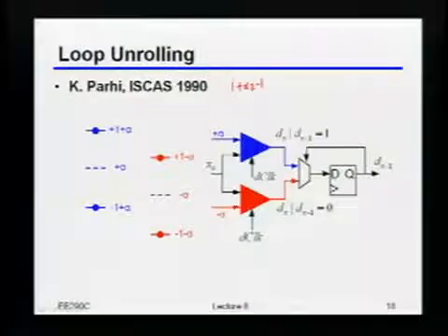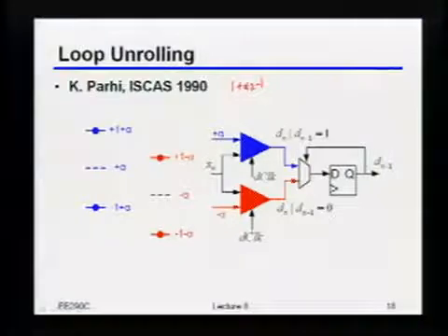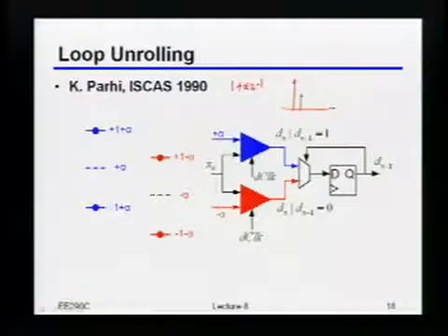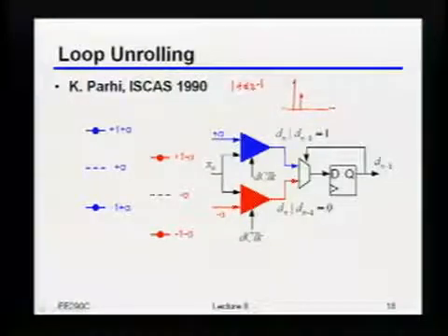In other words, the channel that the DFE has to deal with looks something like 1 + alpha z^-1. That alpha is the value of the post cursor. Usually in a high-speed link, that value is positive, but it doesn't necessarily have to be the case. In this particular example I've assumed that alpha is positive, meaning I'm assuming my channel looks something like this. I'm still going to close the rest of the taps in that normal summer that we talked about, so I'm going to assume I've canceled those out. But I'm going to see what I can do to deal with this very first tap.